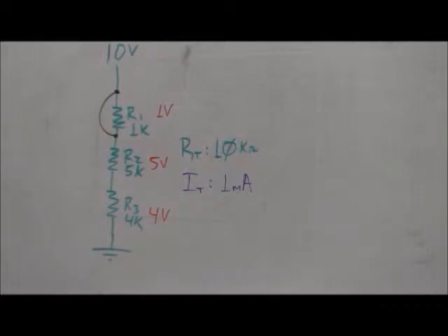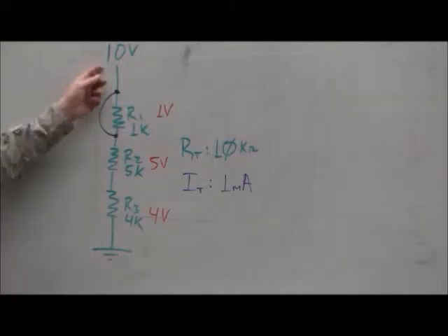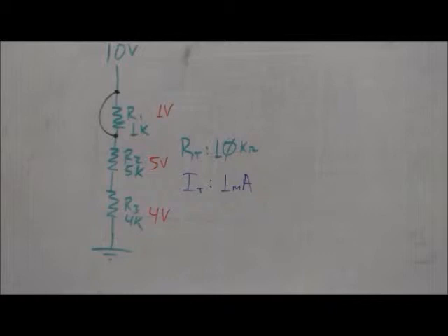Question? Okay. So if we short around R1, our new total resistance would be 9K ohms. Okay? And then if we divided 10 volts by 9K ohms, someone got that? 1.11 milliamps. So we see that our current did in fact go up while our resistance went down.